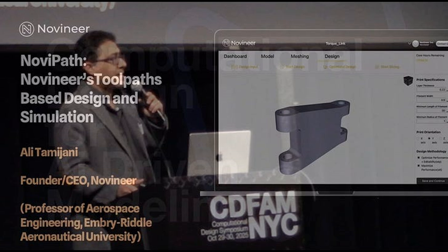And again, here you can see the deformation, and then afterwards you will see the comparison between the failure loads between the two. So again, for this one, you see it's saying it's going to fail here. So here you see the failure loads for these two cases. And for load case 2, you see the difference is about 5%. So great, right? For load case 1, you see the difference is about 18%. It's not bad still for simulation versus experiment, but it's not great.